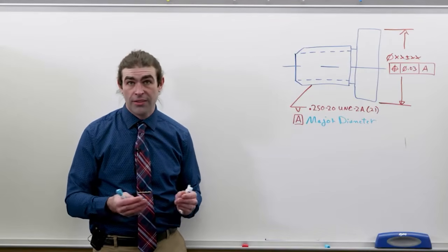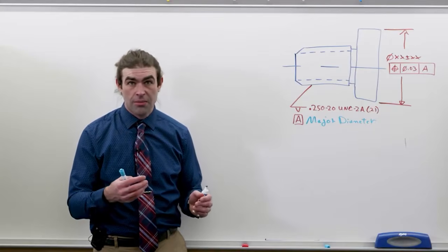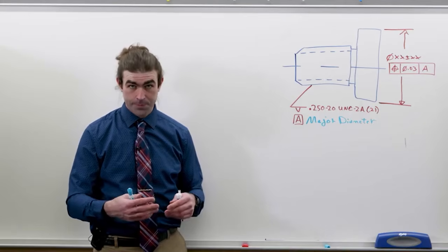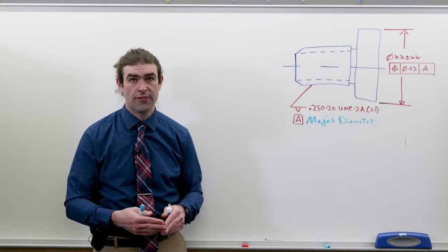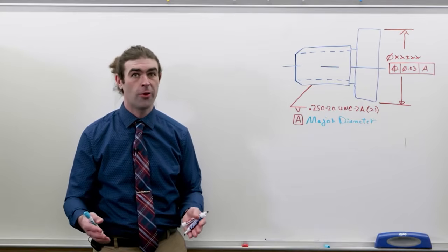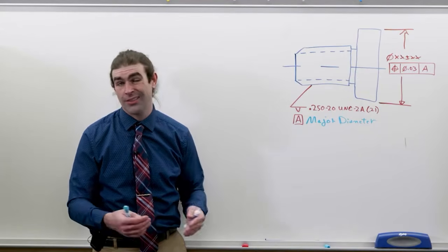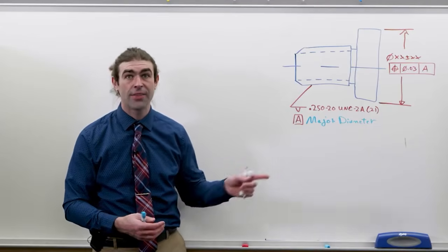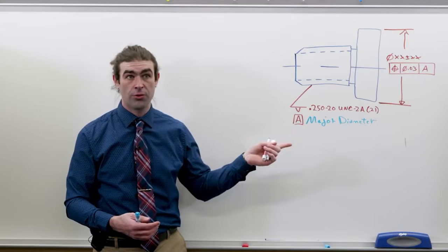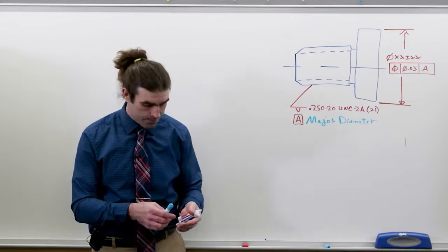The downside, design-wise, is that the major diameter doesn't locate the thread as good as a pitch cylinder, so you wouldn't want to do this if it's really critical to locate something. I mean, you really shouldn't use threads to locate things, but I guess it just depends on the stack up you're looking at. This could induce error at assembly that's difficult to keep track of. Right?